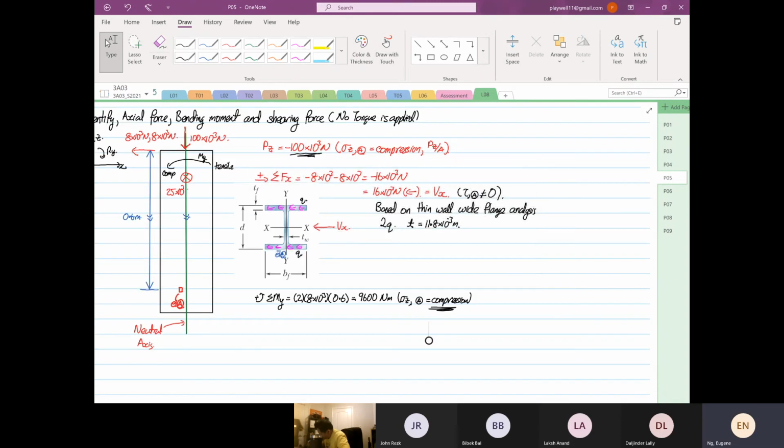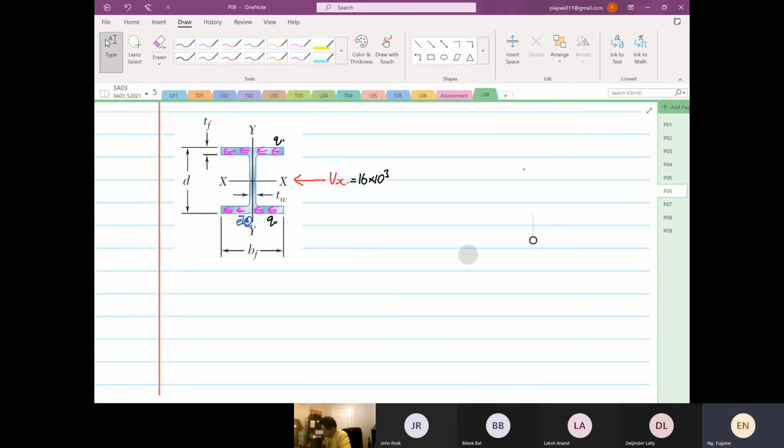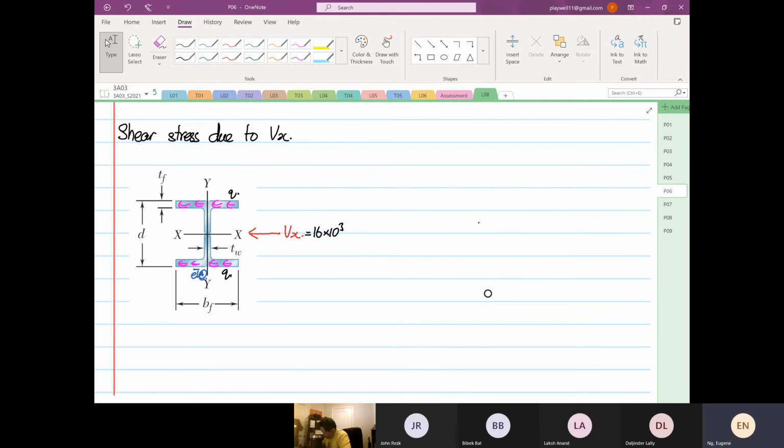Wide flange analysis is not 2Q, okay, it's Q, right? Box beam, then it's 2Q. Right, so over here, we know that we need to consider this area over here, right? If you look at the rules, we're going to use the analysis starts from the what? The maximum distance from the what? From the centroid. Yes or no?